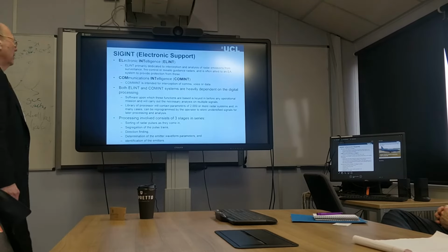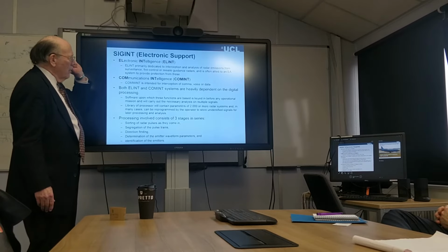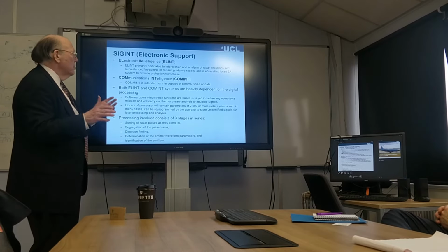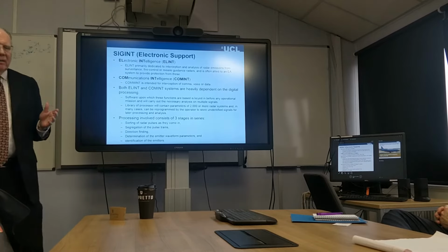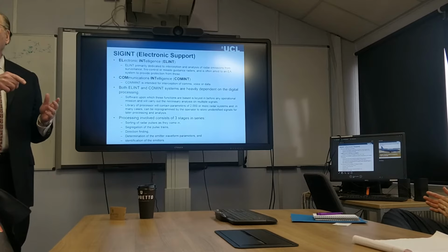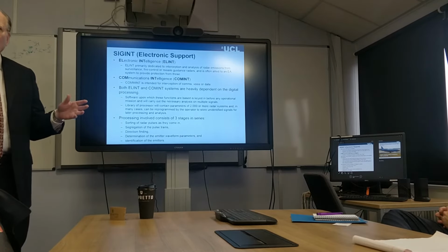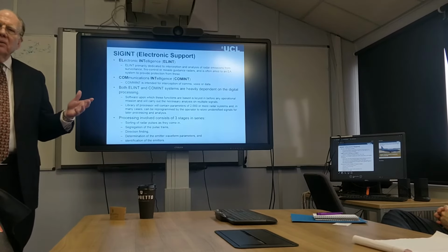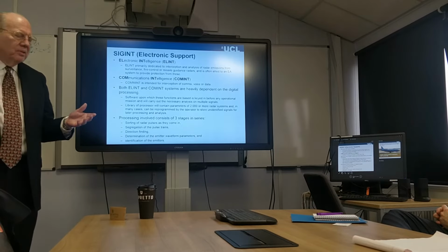And the aircraft have specialized receivers that receive the radar signal, and they use that signal to find the location of the radar. One of the important things is where that radar is located, and then they also look at the different modulations the radar has, the RF that it has, what its beam shape looks like.